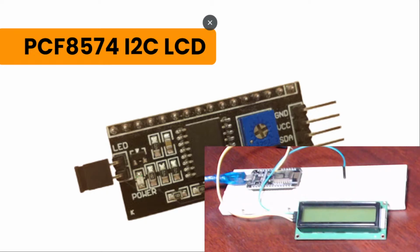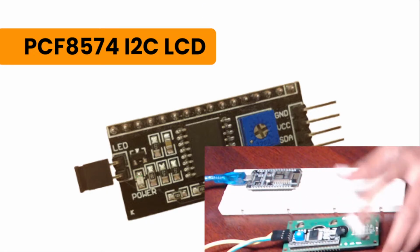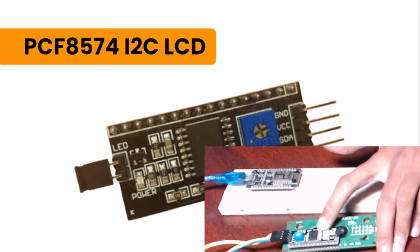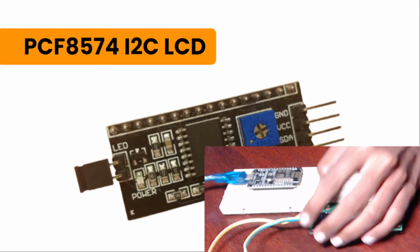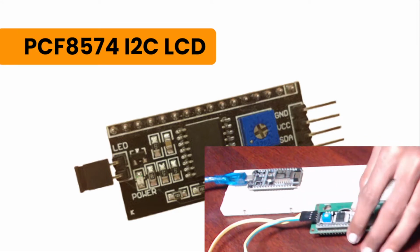Let me show you the module. So this is a 16x2 LCD, and on the back side we have to fix the I2C LCD module here, PCF8574. And we are going to use only these 4 pins: VCC pin, ground pin, data pin and clock pin. Only 4 pins.